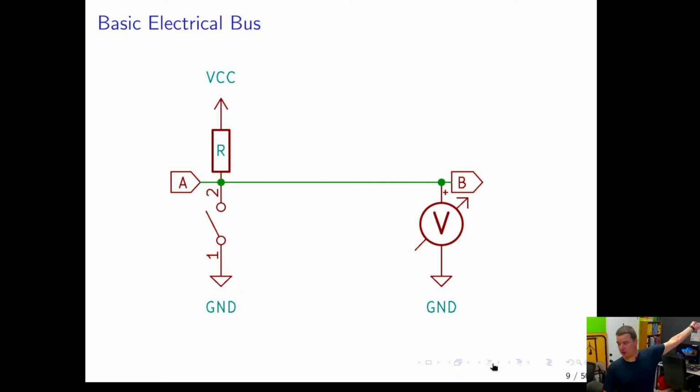Of course, you have to agree with node B on the clock situation. Either you have another line that provides the clocking, or in the case of CAN, and actually I think serial also, you just agree on what you're doing. Like we agree that every second 1 bit is being sent down the line.